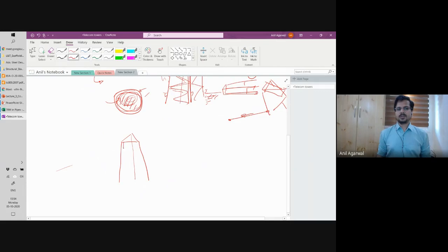So the main legs will typically be your tubes, okay? And then you have to do the splicing between the main legs. Other than that, you don't need much connection. So the splicing is typically done with an end plate kind of a connection. So you have a tube, the tube is pre-welded with an end plate, which has some 6 or 5 holes or 4 holes, something like that. Then there is another pipe with another end plate connected to it, which also has these holes at the same location. You put them together and you put bolts through it. So these are basically bolted connections. That's how you do the splicing. Other than that, you don't need any other connections on the main members. The main members are all continuous.